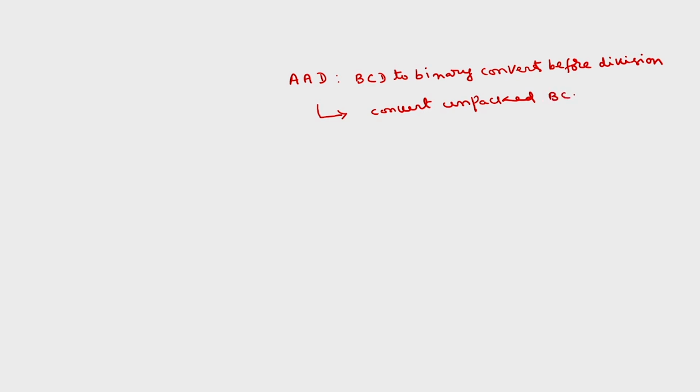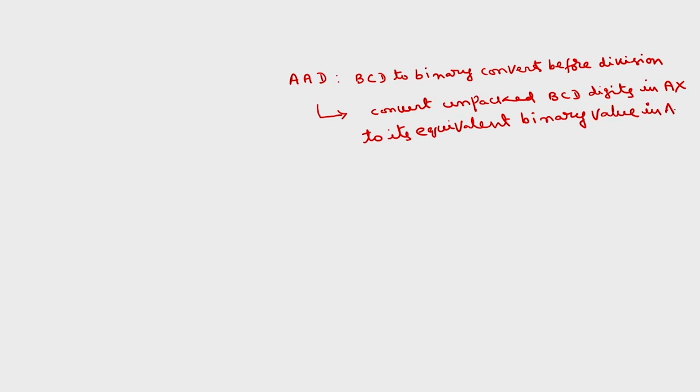It converts unpacked BCD digits in AX, this implied register is AX, to its equivalent binary value in AL, this is also implied.